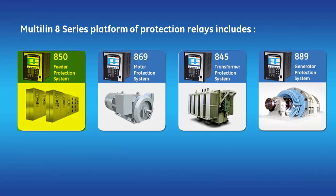850 is an advanced feeder protection relay that provides high performance protection, high density I/O, extensive programmable logic, and flexible configuration capability. With protection and control logic, 850 allows for simplified coordination with upstream and downstream disconnect devices. Additional control features such as auto transfer scheme, load shedding, cold load pickup, and auto reclose are also available for optimal protection and control of industrial and distribution networks.